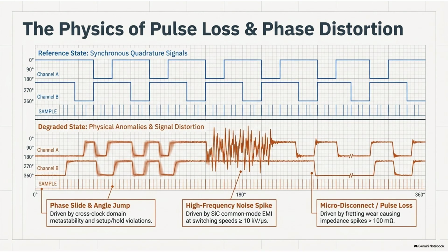And the first line of defense is hardware pulse diagnostics. Okay. The microcontroller's hardware timers are constantly running a plausibility check on the signals. For optical and magnetic encoders, the A and B signal pulses must strictly maintain a 90-degree phase difference, which is known as quadrature. The 90-degree offset is fundamental, because if signal A and signal B were perfectly in sync, the computer would only know the speed of the motor. Right, it wouldn't know the direction.